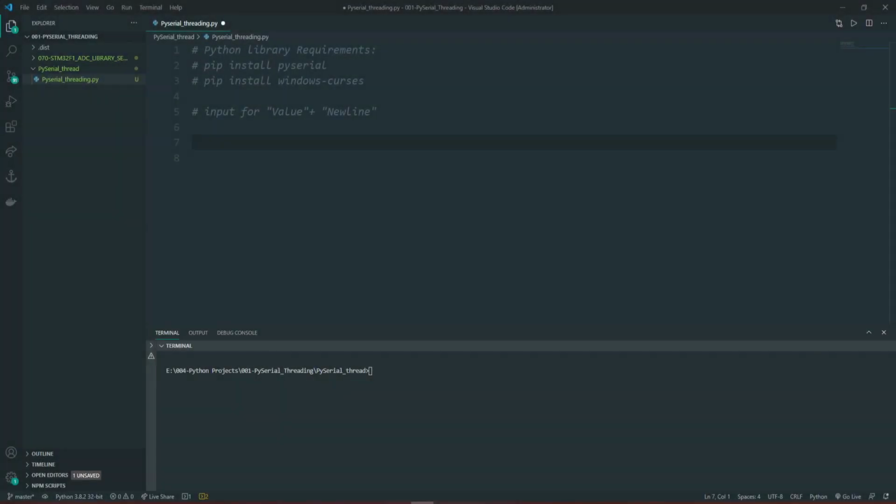So this is the first part where we start reading the serial data from whatever the microcontroller, not even the STM32F1, but also Arduino or PIC. What we have to do first of all is to install the PySerial library. It's quite simple and easy. Let's just copy this one and pip install PySerial. I already installed it, so no need to stop there too much.